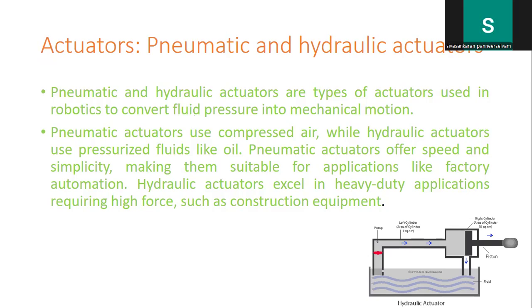Pneumatic actuators use compressed air, while hydraulic actuators use pressurized fluids like oil. Pneumatic actuators offer better speed and simplicity, making them suitable for applications like factory automation, whereas hydraulic actuators excel in heavy-duty applications which require very high force, such as construction equipment.